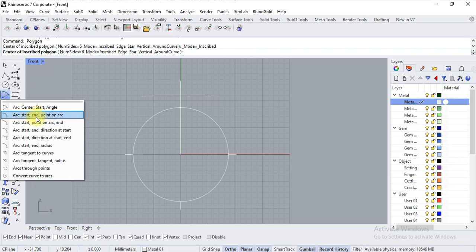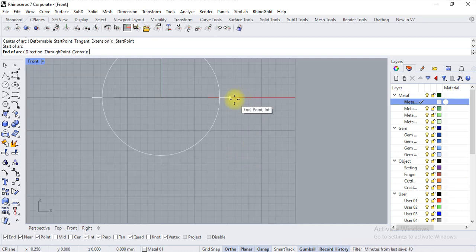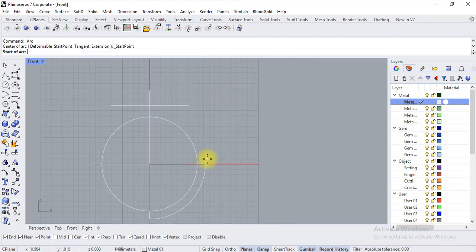The second click will create the end point, and then in between that arc, I have to specify one point. Suppose this is my first point, this will be the start point. Turn off ortho, second point, and now the third point, the point on arc. Just type in any value. Okay, this is fine. Now again first, second click, and adjust the curve.